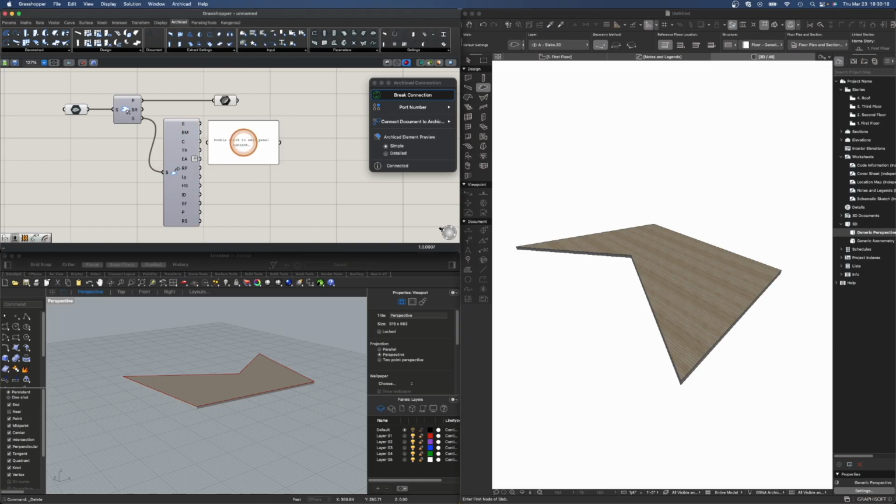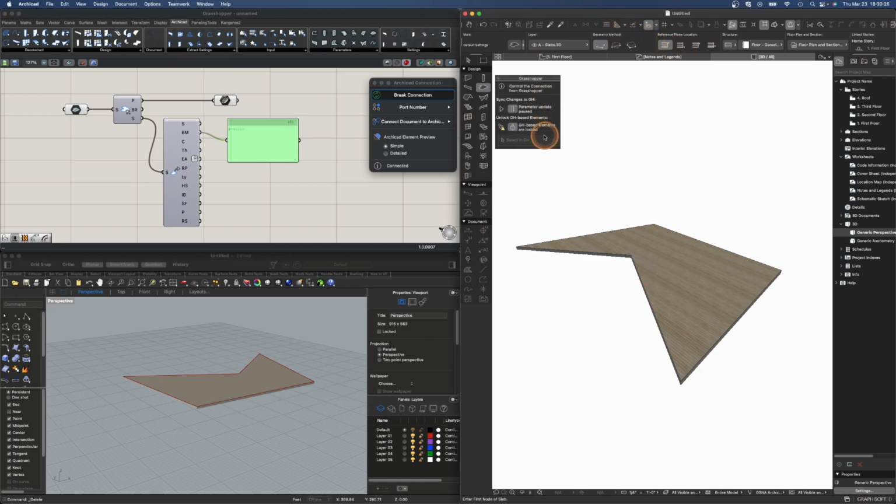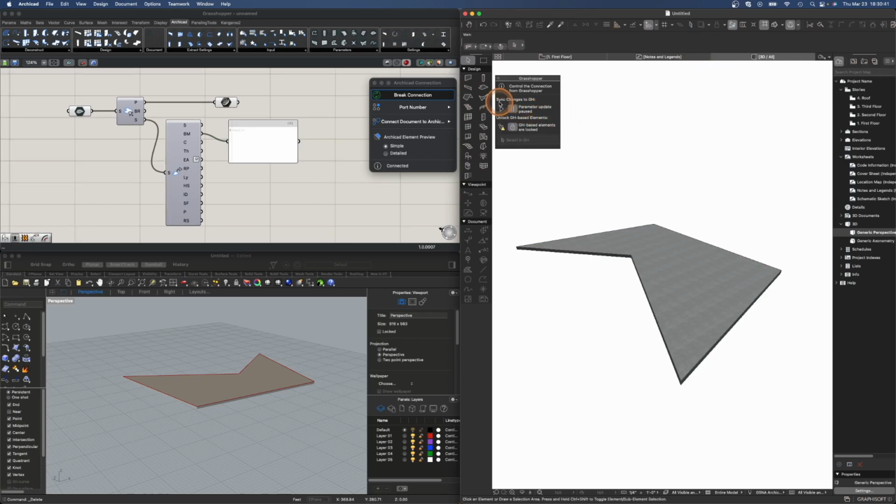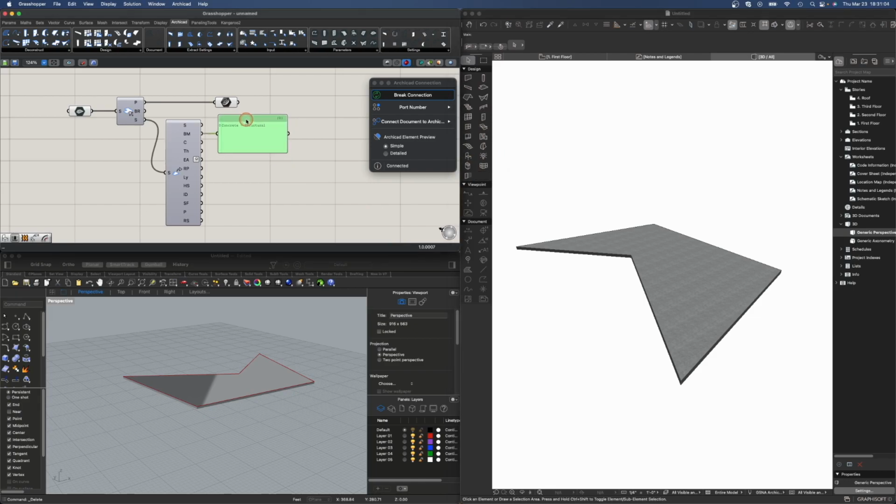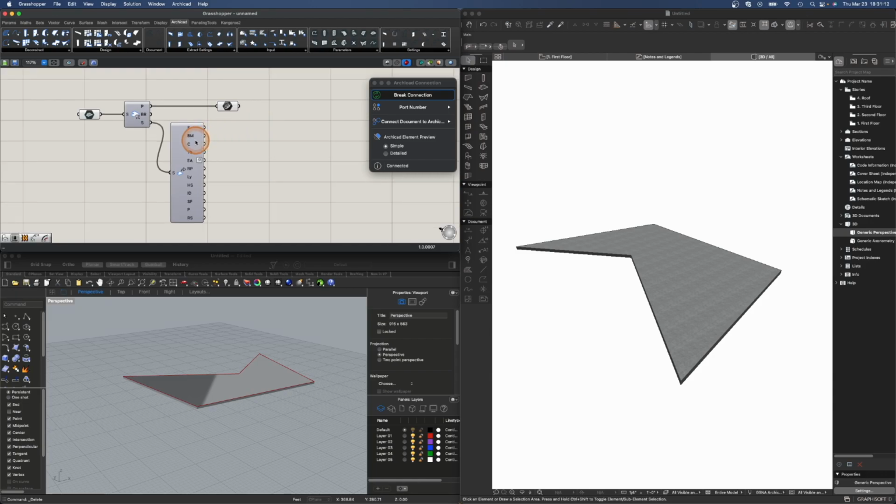Let me place a little panel inside Grasshopper to show you what that building material is. I will get an error message because I'm actually using a composite structure instead of a single building material. And one thing I forgot to do is to set the Archicad palette to sync changes to Grasshopper. You typically don't want your computer to push data constantly. You want to have some sort of a gateway there. Okay, so you can see that as I change the material inside Archicad, it updates in Grasshopper as well. And then you get access to multiple parameters, obviously.